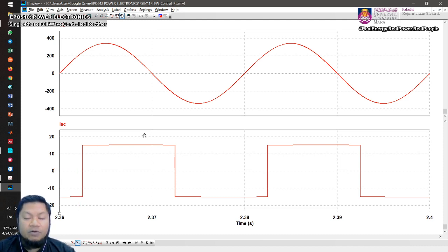Okay, in this case, if you look into the Fourier series, the Cn, which is the harmonic content, the amplitude of the harmonic series, will be the same as the square waveform that we had before, which is Cn equals 4IDC over n pi. So this is your IDC, isn't it?